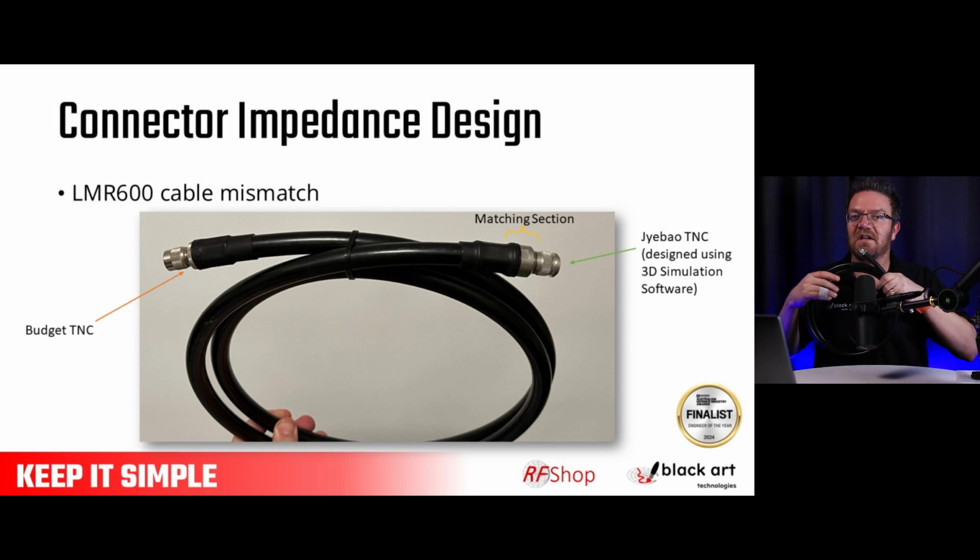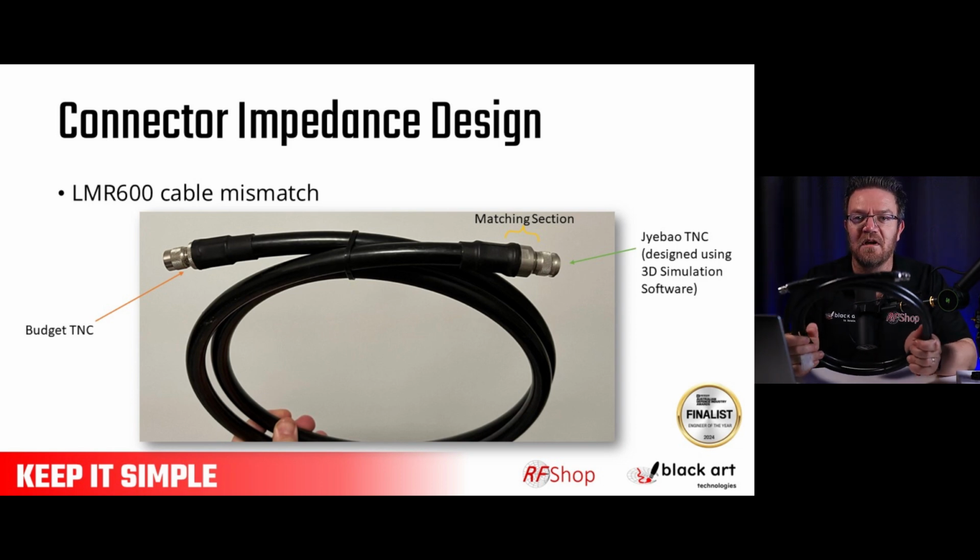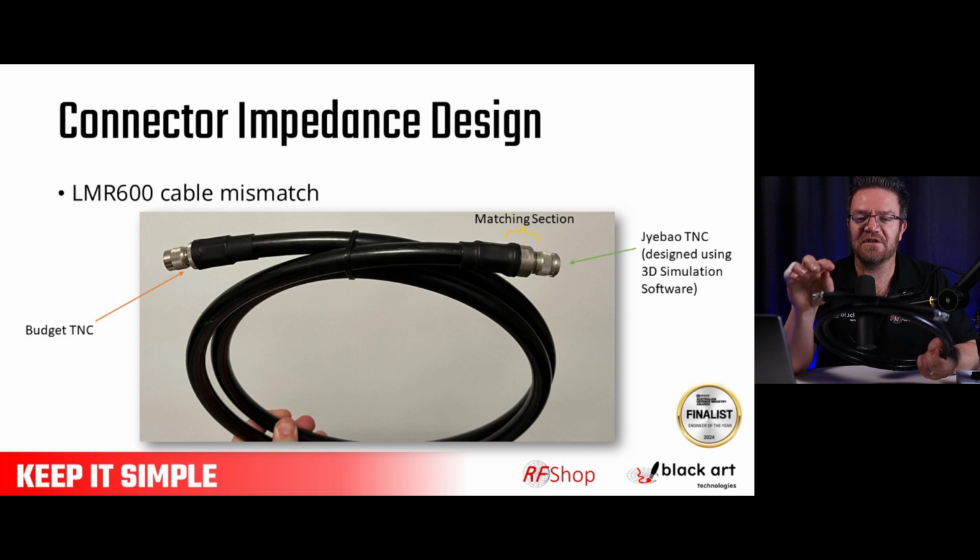And this, again, becomes really a real case problem that I would have had in my own life. So there's the cable that I show you on the photo. What we saw was, we just thought we'll put a connector on LMR 600. This is a while ago, so we've learned our lesson. Don't worry about that. But we used just a connector from a supplier. And it is basically TNC to LMR 600, and we had massive issues with performance of the cable.